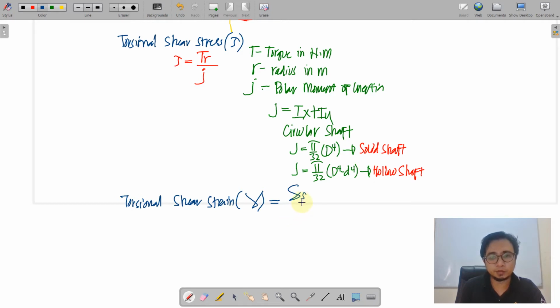Here we have a subscript S, to indicate that this deformation is a shearing deformation, all over length. Further, remember that this deformation is associated with an angle. So the formula of the torsional shear strain expands to writing the shearing deformation in terms of radius times the angle of twist, then we just copy the divisor length.